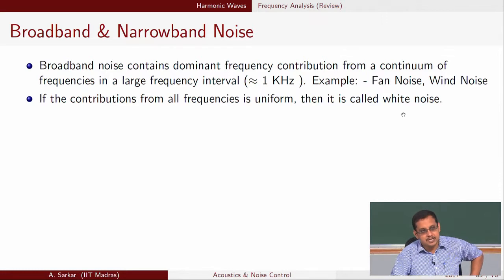So, white noise is an example where there is absolutely no correlation between the values of the signal, and if there is no correlation, then all the frequency content is spilled onto the spectrum, and that is why we call it white noise. What we did the other day in the MATLAB illustration, when we asked MATLAB to generate a few samples of random numbers and played that out, it created a hush hush sound, typical of, let us say, the sound of the AC that you are hearing right now. It also has quite a dominant component of white noise.